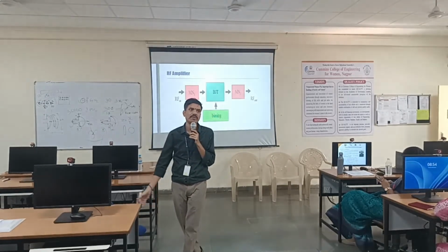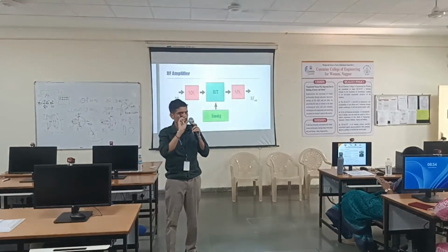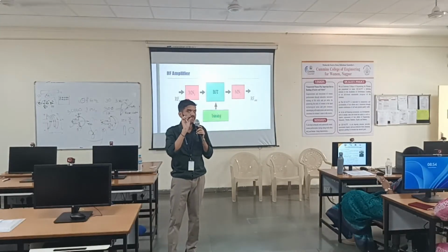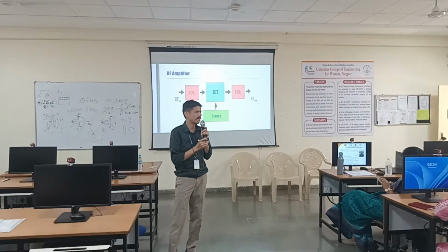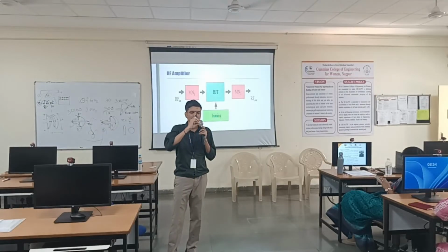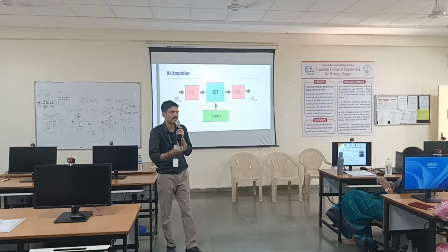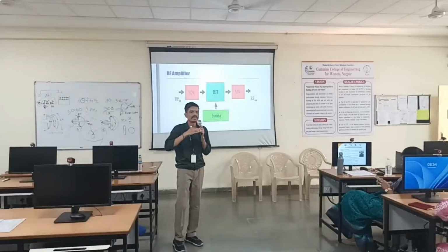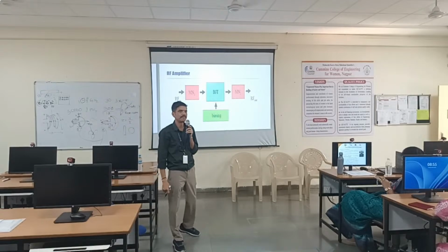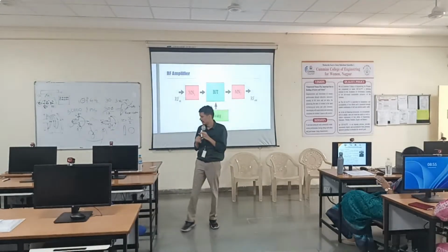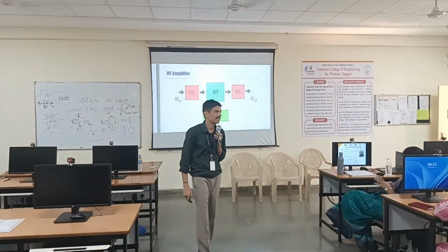Width is going to decide the impedance. The larger the width of the transmission line, the smaller the impedance, and the smaller the width, the larger the impedance. So you can see different microstrip circuits where you see some minimum width, then the width is increased. I will show you in my design. Impedance is being changed in steps, and that is called a stepped impedance filter. So width is the parameter which decides the impedance of your transmission line. Any other question?